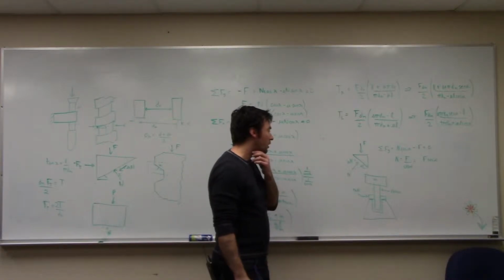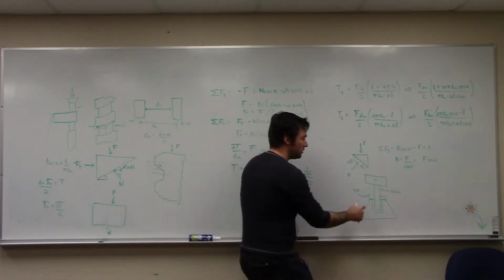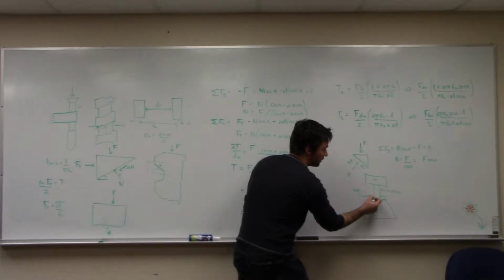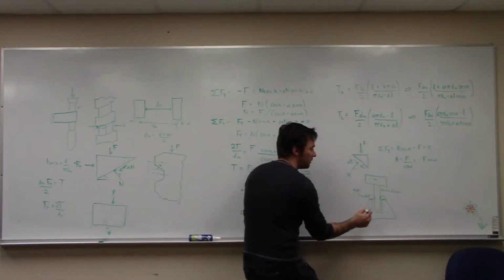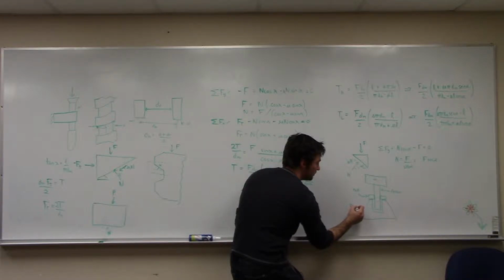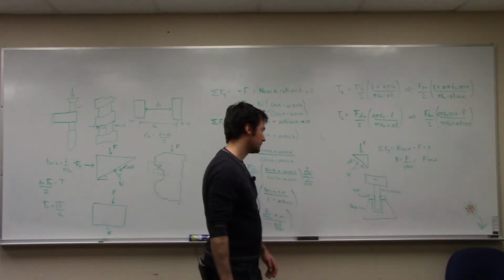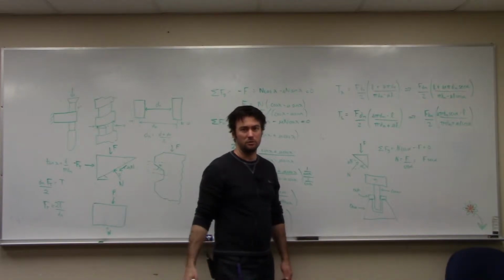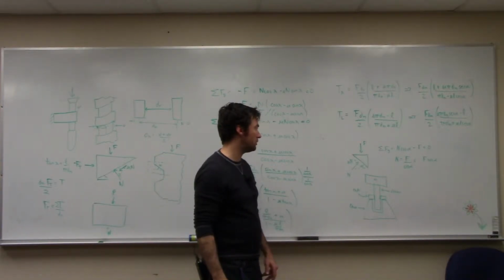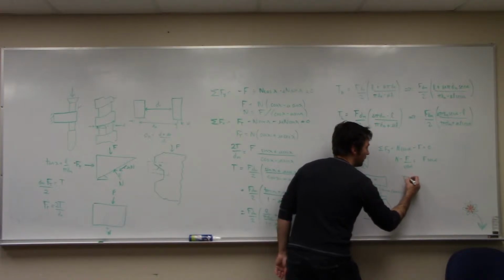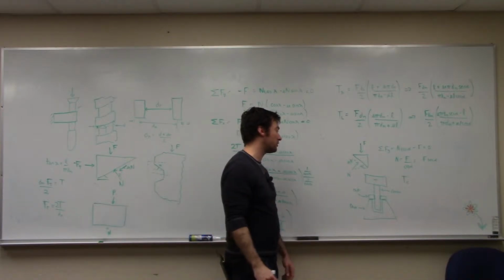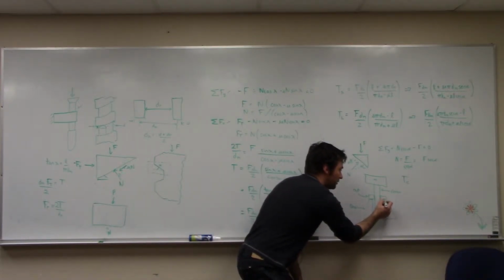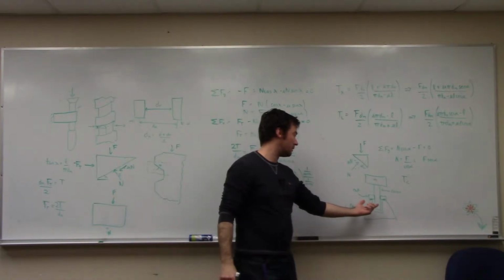But you can see in this case, we also have another instance where, in addition to friction at this interface here, between the thread and the female thread, we've also got some friction because we're rotating the nut relative to the base here. And that's pretty easy to model. It's a lot easier than the screw. So let's do that really quickly. The torque due to, we call it the collar torque. The torque at the collar. It's because there's some friction force that's acting at this mean radius, at the middle here.